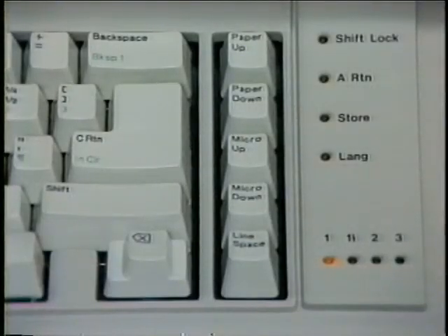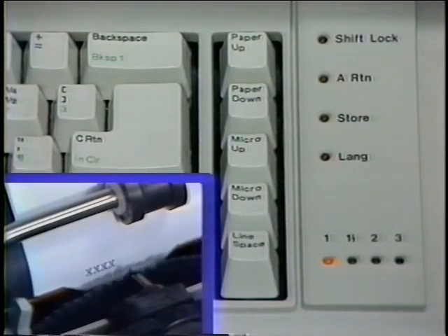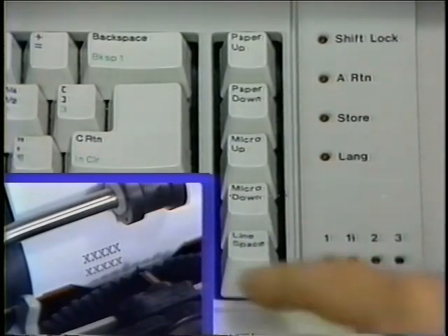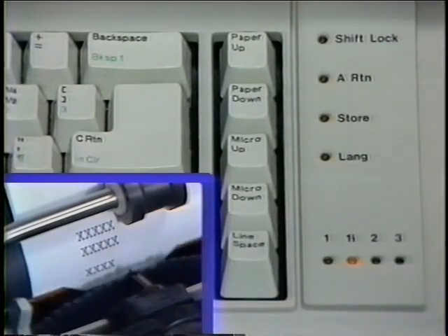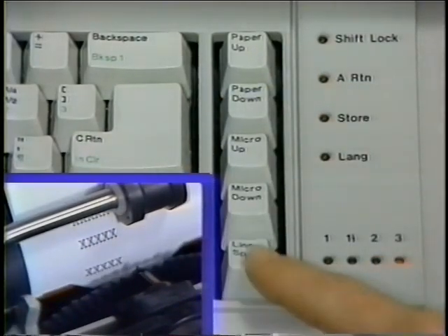The 4 lights across the bottom of the indicator panel indicate which line space setting the machine is set at. When the machine is turned on and completes power on reset, it is in the single space mode and the single space indicator is on. Pressing the line space key button causes the machine to go to the next higher line space setting until it reaches triple space. After triple space, the machine returns to the single space mode. The line space setting only affects the amount of paper feed during a carrier return operation. It does not affect the SAPI operation.